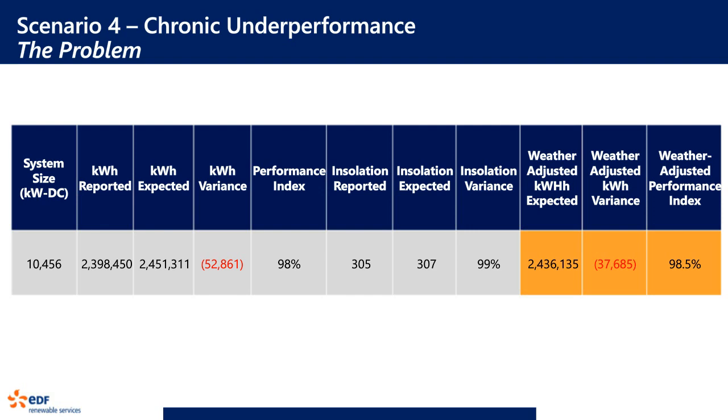And this gets a little trickier to do when you're chasing what I call phantom problems around. We were able to see that there was, for instance, an inverter fault on the 13th, and by doing a lost energy analysis of that, we found approximately 0.25% there. We were able to look at another problem and find this. But really, going back and chasing our tails on this over a 3 or 4 month period, we were still just seeing this persistent 0.75% to 1% that could not be explained. There's always some problem that covers a little bit of it, but we never quite get there.